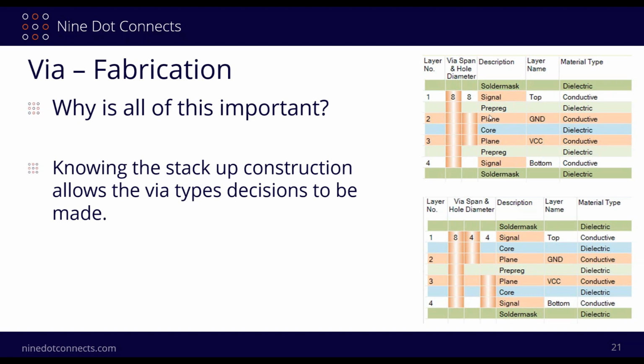So that's why it's really important to understand how they're going to stack this thing up. And that's why you want to have that conversation with your fabricator, because in one situation here, this works really good for a buried via, and the other situation works really good for a blind via.